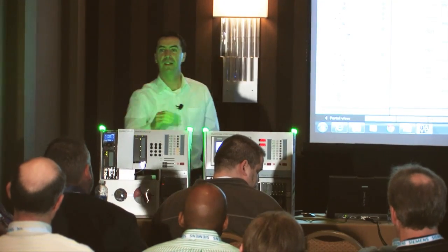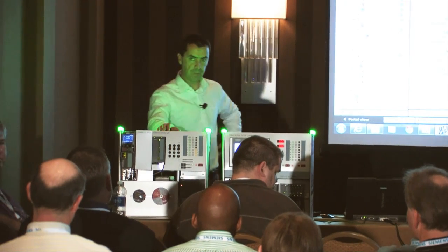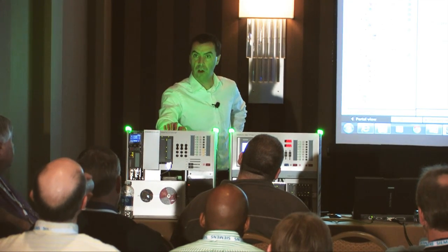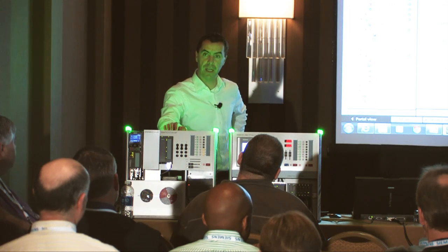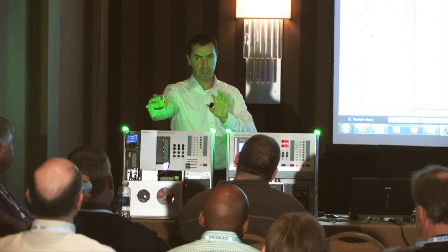Go ahead. When you have all the PLCs and HMIs in one project, how do you manage multiple developers, programmers? Offline, the way to do that is with the global libraries, like we just talked about earlier. That's how you can bring them in together. So, they would work independently and then merge them together at some point. That's a manual process to merge your PLC and HMI stuff offline.